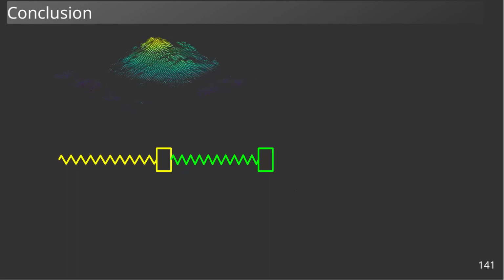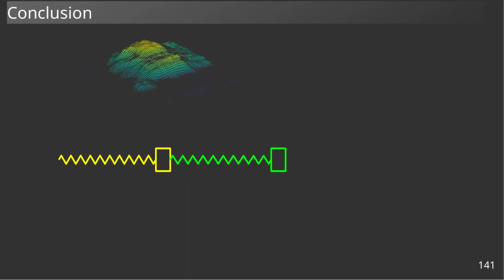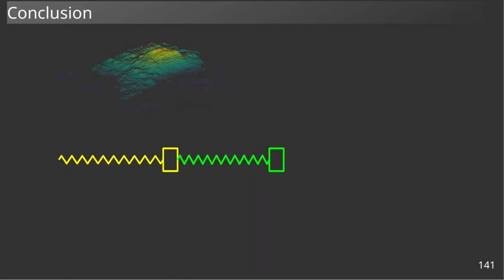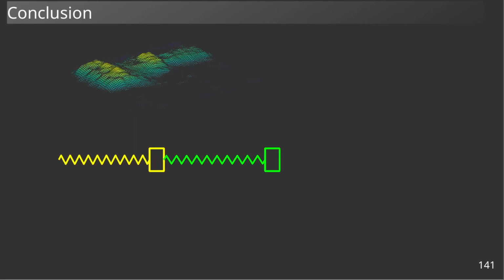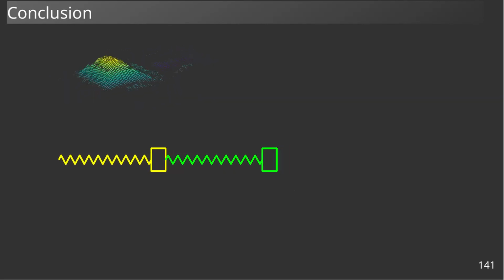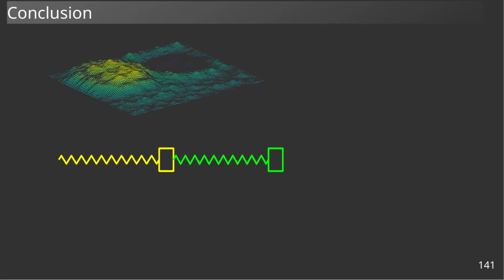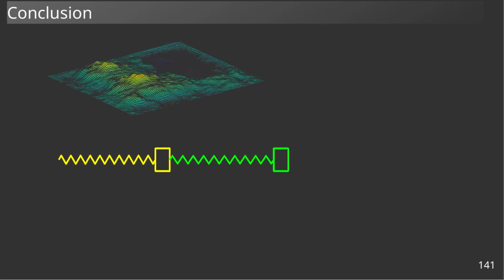It should be noted that modal analysis can also be used to study discrete systems, such as this pendulum. In this case, we are not dealing with an infinite dimensional space, the dimension being this time the number of degrees of freedom of the system. These are vector spaces, and the mass and stiffness operators are then matrix operators.